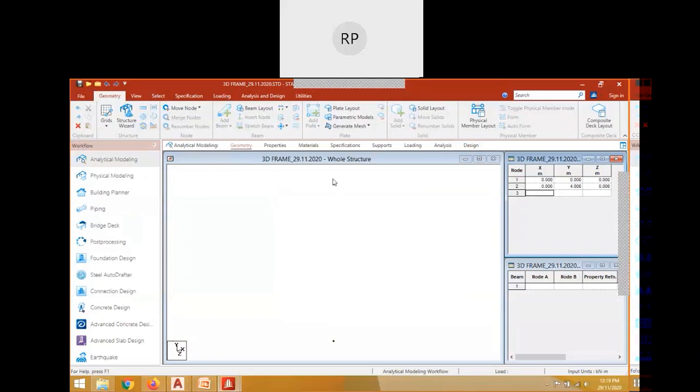Now from here, this is the level. Which is this level? This level is nothing but a plinth level. What is this level? This level is nothing but the connection of foundation with your column, right? So these two levels are created. Now I will create the levels above this. First level is a ground level, which is having a height equal to 3.1 meter.